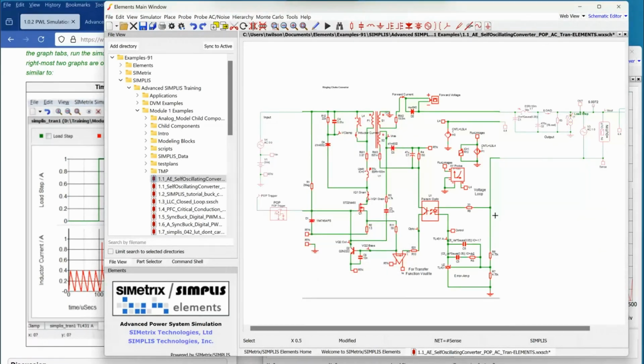Here's our feedback. Resistor divider feedback, we're using a TL431 with its compensation as our error amplifier. We're going back across the isolation boundary with an opto-isolator. And you can see this is a self-oscillating circuit. So here's the main power switch.